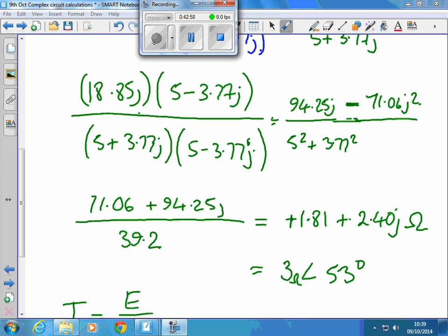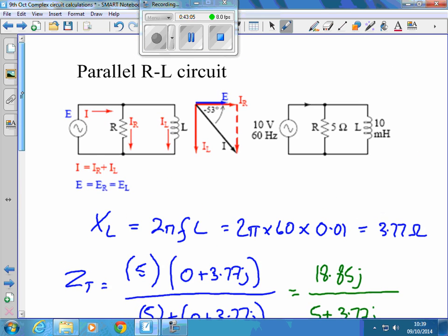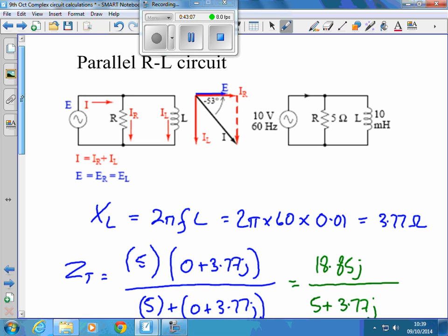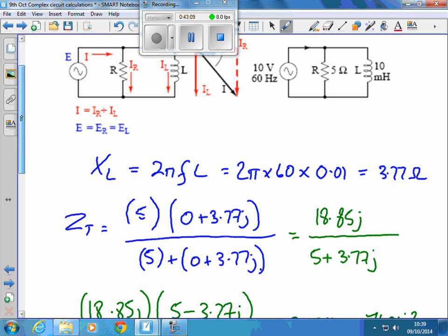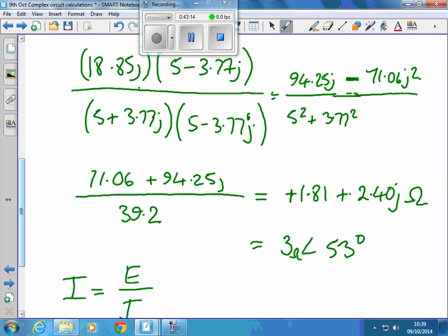That angle is 53 degrees. Where I noticed that was going back to the original phasor diagram and knowing the circuit is inductive and therefore the impedance should have a positive angle between 0 and 90 degrees. Can't go beyond the 90 degrees of a pure inductor. So the 127 degree angle, immediate flag came up there saying something's wrong here.